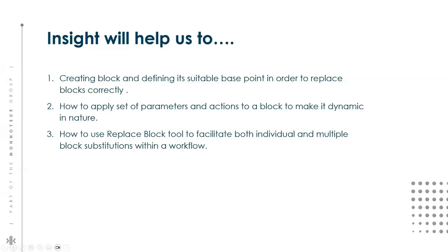In this insight, we will be covering first creating a block and defining a suitable base point to it so that we can replace the blocks correctly in the order we want. Secondly, we would be looking at how to apply the parameters and actions to a block to make it dynamic in nature. And third, we are going to see how to use the replace block tools that can facilitate both individual and multiple block substitution within our workflow designs. So let's just move on to the live demo now.